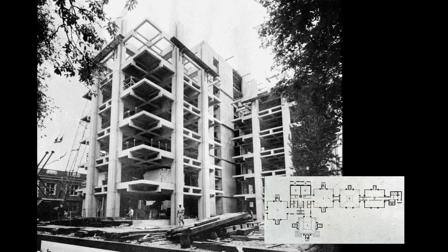Furthermore, when we take a look at the structural supports here, we see that the structural supports are down each side of the square lab floor, but at third points. What does that mean? Well, that means that there is no structural support right at the corner. And so the structure that cantilevers out to the corner, as any cantilever would, doesn't need as much material to